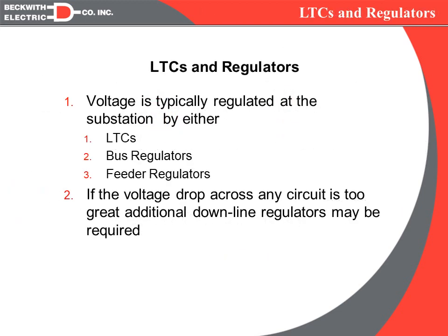So, with that in mind, for this type of system to work, we're going to need regulation inside the substation. We can use LTCs, but it's really recommended to go with feeder regulators. We can go with LTCs as long as the load between the phases is fairly balanced, and as long as we fairly balance out the line losses in each of the circuits. But again, on any of these systems, feeder regulation will give us a better resolution, because we'll be looking at each feeder as an individual zone, as opposed to LTCs where we're looking at each bus as an individual zone. The bigger the zone, the harder it is to coordinate.